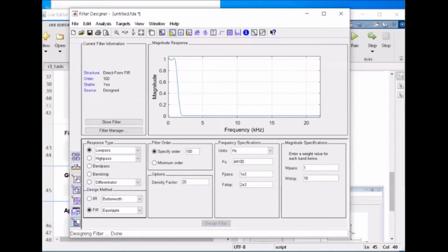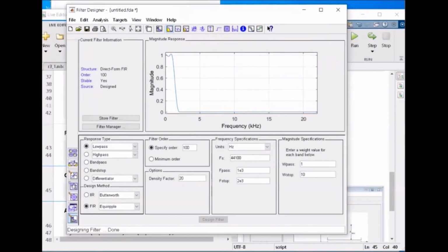When I replace this number and also design the filter, you can see here now in the stopping band, we have a very nice characteristic, amplitude is 0, but in the passing band, it's not so precise. Okay, do you have, please, a question about designing a filter using this filter design graphical user interface?